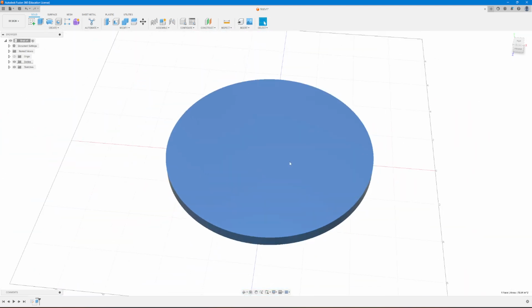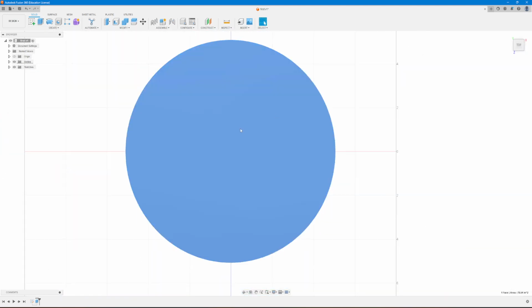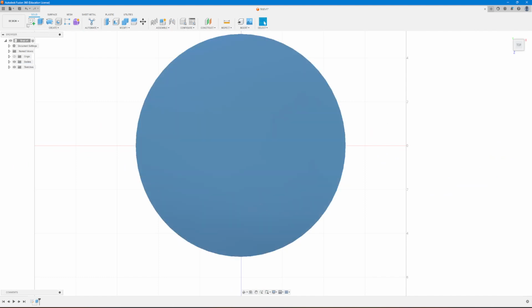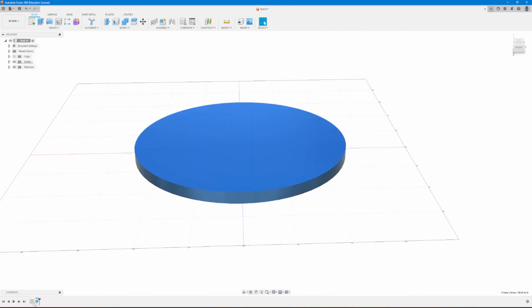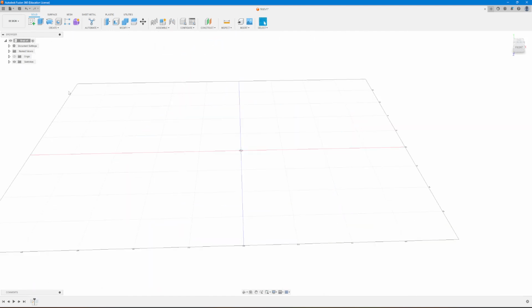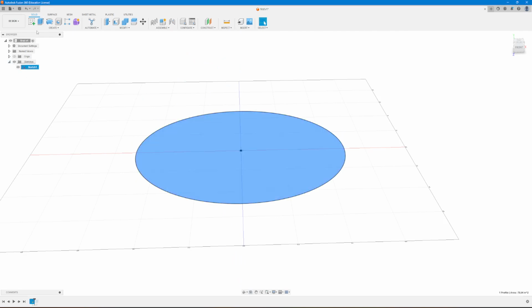If we want to modify this object, yeah, let's go ahead and modify this object. Let's go through the whole process, right? So we created our object. We created it with a sketch, and we extruded it. And I didn't talk about extrusion, so let's go back to that. So we have our sketch, and we want to extrude it. So we're going to go back up here to create. So the sketch has been created, which is the first one. The object has not. So we're going to create the object by extruding the sketch, right?